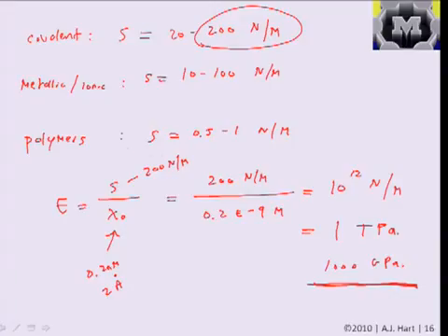So in comparison to this model, or this limiting value for graphite, which is probably one of the stiffest, if not the stiffest material we can think of, why do polymers have such low stiffness? Maybe getting back to what's bonded to what inside a polymer. Anyone give it a guess? The bonds between polymer chains are primarily due to van der Waals forces rather than stronger ionic or covalent.